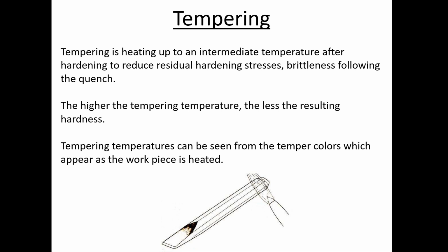The tempering process takes the stresses out of it, because the hardening and quenching process causes a lot of stress inside these higher carbon pieces of material. And if you don't temper these, and the old term, if there's any old people in the room, the term used to be drawing back from hard. What it means is we have to take a little bit of the hardness out of it and temper it slightly to make sure that it's not ready to shatter as soon as we touch anything. This is most of the reason.